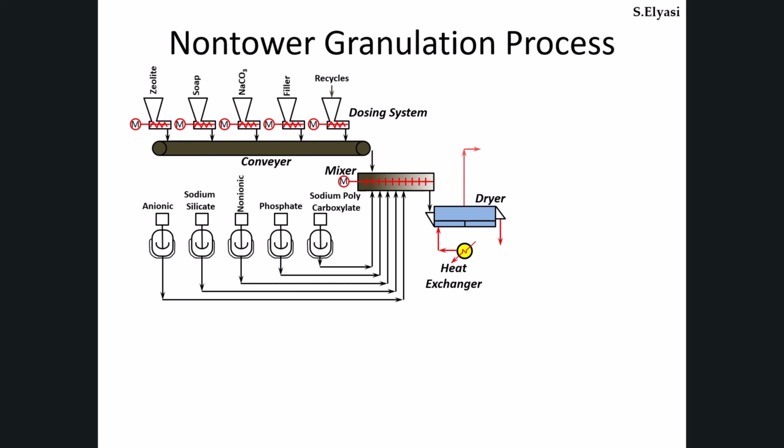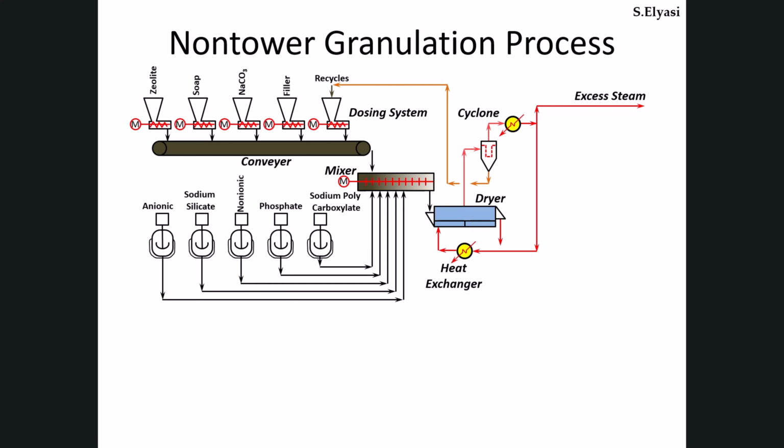The outlet vapor and entrained fines are typically handled with a cyclone, and recovered solids are recycled. In some designs, part of the steam vapor stream is recovered for heat integration, and excess steam can be used elsewhere in the facility as a heating medium. After drying, a vibrating screen ensures a controlled particle size distribution. Fines may again be recycled to stabilize product quality.